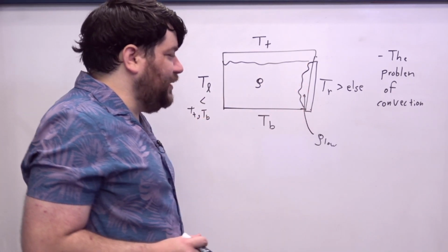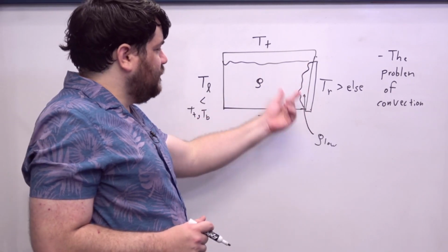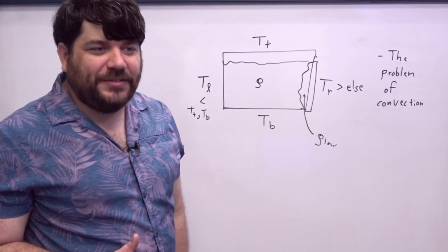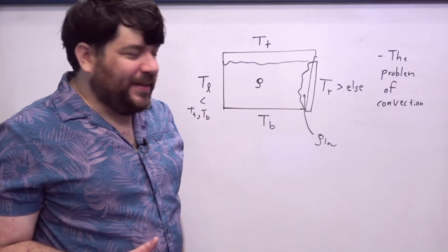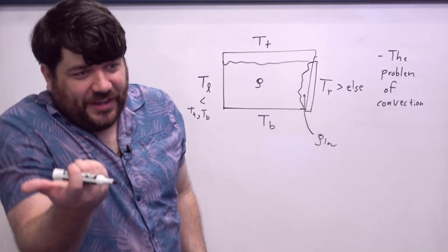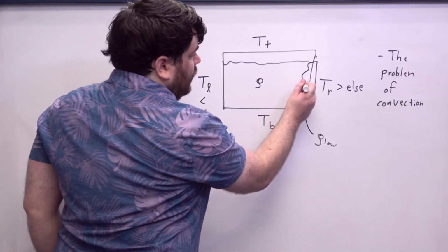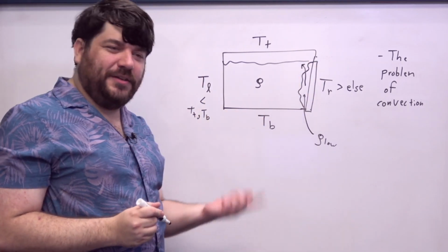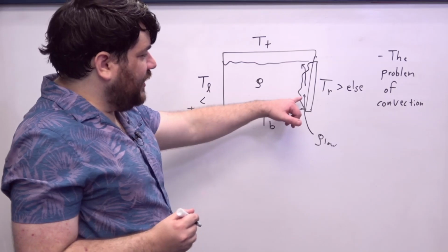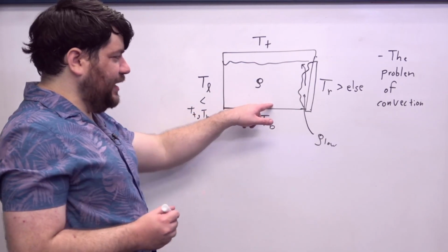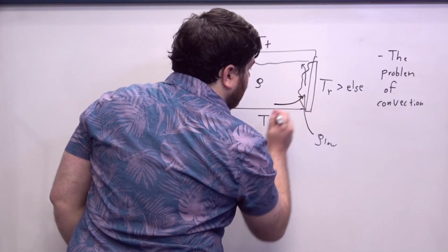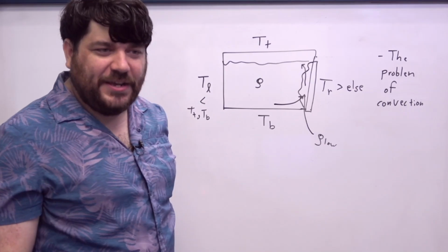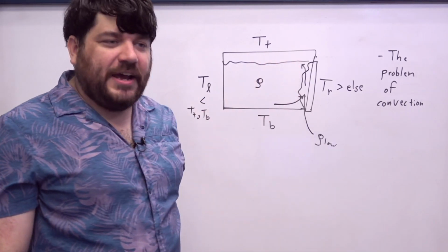This patch of liquid behaves like it's basically a submerged object that has a lower density than the background density of the liquid. And so as a result, it starts to rise up, just like any other object which is buoyant. And so you start to observe that the liquid flows upwards. This little hot patch of liquid flows upward. In order to prevent a vacuum from developing, of course, liquid that is over here at the bottom has to be pulled in over to the side to make sure that you don't get cavitation, so this doesn't generate a vacuum.